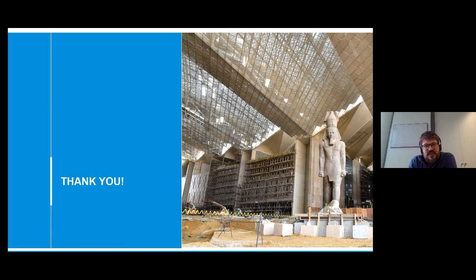Then it's something you can talk about during another session also. But indeed, when you need to repair something, you first need to understand the cause, to avoid that it's going to occur again. If you remember one of the first examples I showed in Mozambique, it was absolutely necessary to understand the cause of this corrosion, and it was coming from the inside because of the seawater that they used in the mix design. If we hadn't looked at this, we would have repaired everything, and then the corrosion would have continued from the inside. So first, you need to understand the cause, and then you can repair by a lot of different methods depending on how big the problem is and where the location is. But that's really another discussion. There's a lot of different possibilities.